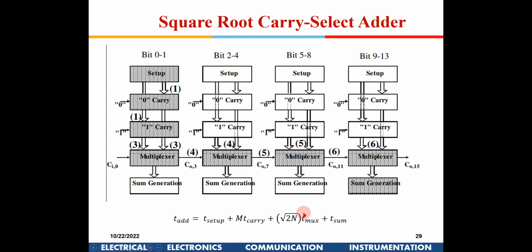So obviously this is better. Now this is a graph which shows this is the ripple carry delay, this is linear carry select as you keep increasing n, and the bottom dark thick black line is for square root select. Is it okay till here? Anybody has any doubts? Is it okay? Yes, shall we move forward?